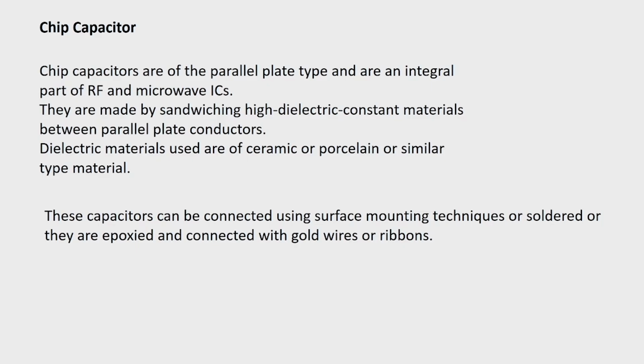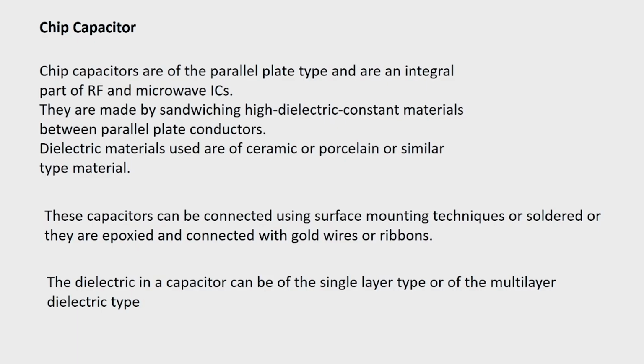These capacitors can be connected using surface mounting technique or soldered, or they are epoxied and connected with gold wire or ribbons. The dielectric in a capacitor can be of single layer type or of multilayer dielectric type. So, this shows the appearance of a commercial chip capacitor.